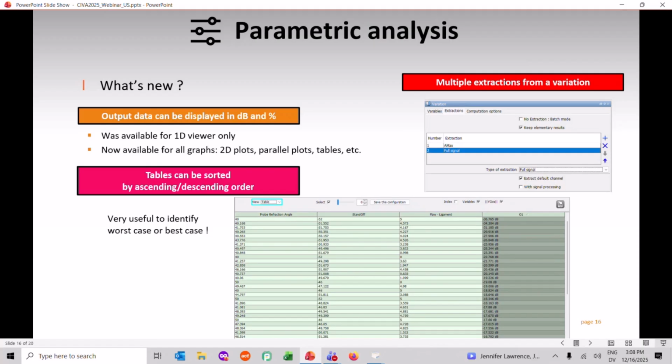And I think this is probably one of my favorite new features for this parametric study module, is now that you can view all those different cases as a table. And this will allow you to sort on the different columns and identify your best and worst case scenario. So before you still have it, you had that graph with all of the lines that were pink and it kind of looked like a big spider web. Now you can switch the view to table and sort on different columns to look at your data. You can also export this as well.